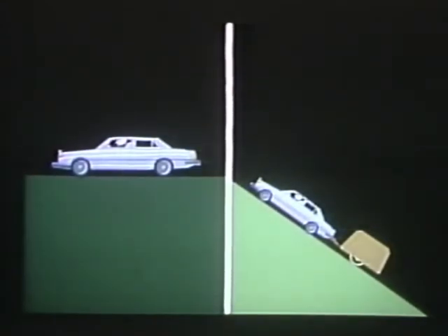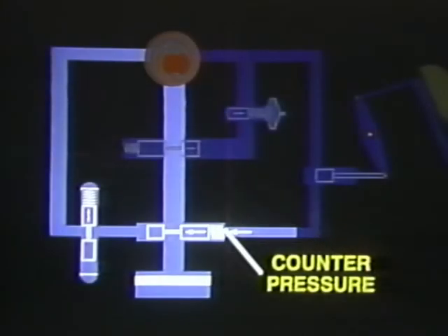Governor pressure would be sufficient to control the shifting of the transmission if the vehicle was always operated under the same load and at the same rate of acceleration. But a vehicle is not operated under a constant load. In fact, a vehicle is operated under very different extremes. Therefore, the transmission must be capable of sensing the actual load and change the shift points accordingly.